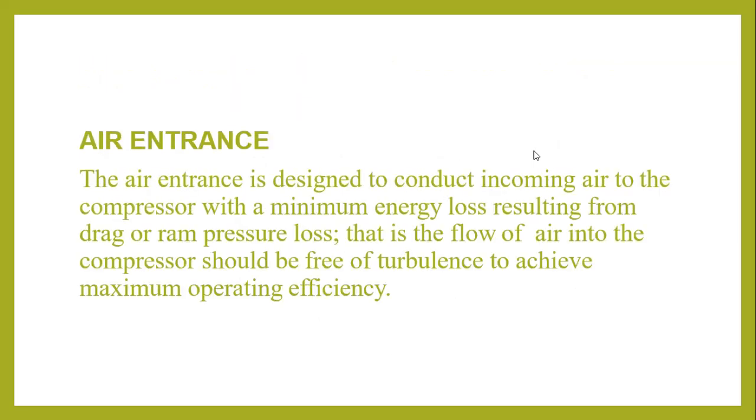So now we go to the air entrance, because you're looking at the main parts of the gas turbine. We have the air entrance, that's for air entry. The air entrance is designed to conduct incoming air to the compressor with minimum energy loss resulting from drag or ram pressure loss. That is, the flow of air into the compressor should be free of turbulence to achieve maximum operating efficiency.